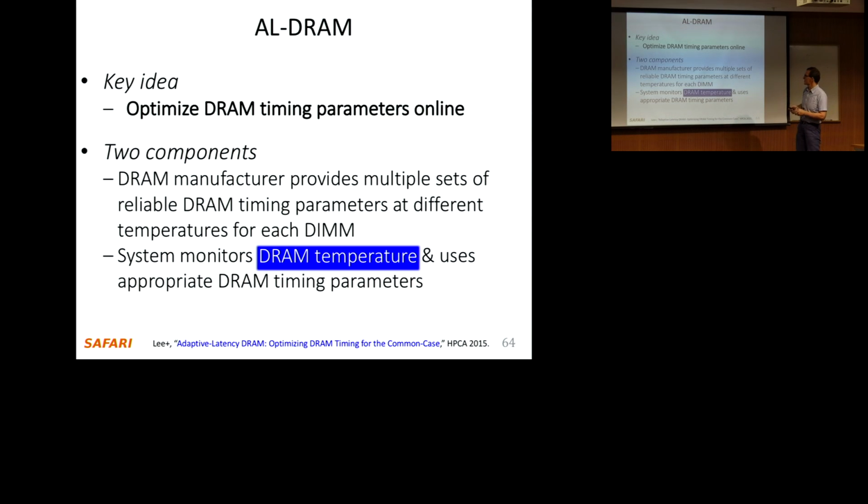Yeah, but I'm suggesting that you do it for each DIMM. Basically, you specify the latencies for each DIMM. The refresh rate has not anything to do with it. I mean, yeah, we're not changing the refresh rate at all here. Okay. That's right. Although the refresh rate is actually, there's temperature compensated refresh in systems today. So refresh rate already adapts to the temperature today, every 64 milliseconds at low temperatures.